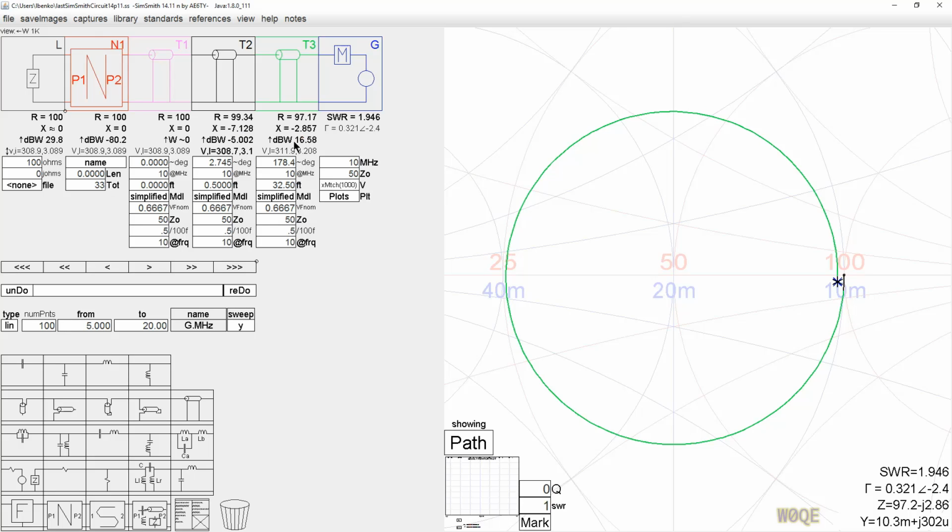So let's change the power now to be this way. This is the power now consumed in each one of these pieces of transmission line. If you had a 1,000 watt generator that was matched to this line, you would generate 45 watts of heat in this line. You would generate 0.3 watts of heat in that short little piece, and no power in this one because it's no length. We have the black sections at the very beginning, so there is no T1 effectively, delivering 954.2 watts into the load. And as we move the little segment around, the 3 pieces of transmission line together don't really change. It's just where this one sits within that group.